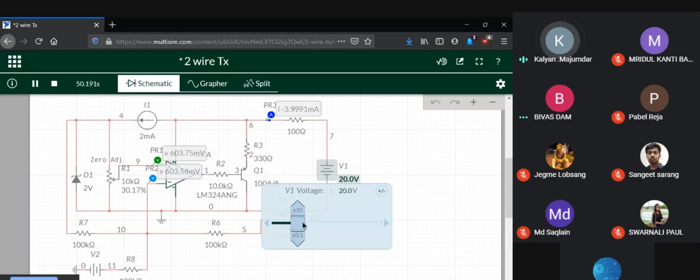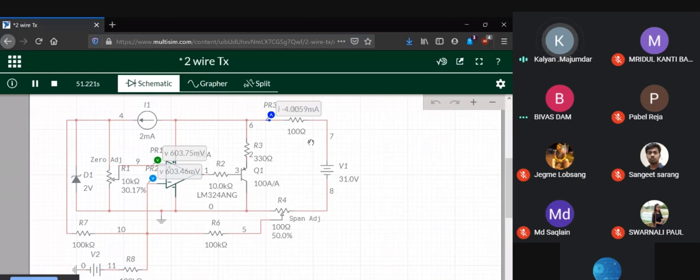So from almost 5 to 50 volts there is only a change in the third position of the decimal. That way you can find out that this current is both independent of the supply voltage fluctuations and the load resistance fluctuations. That is how it should be, because this current is also the current flowing through the indicator. This is responsible for the indicated value, and it should solely depend upon the input voltage. It should not vary if there's a change in the supply voltage. It should not vary if there's a change in the load resistance. That is what is expected, and that is precisely what is happening.